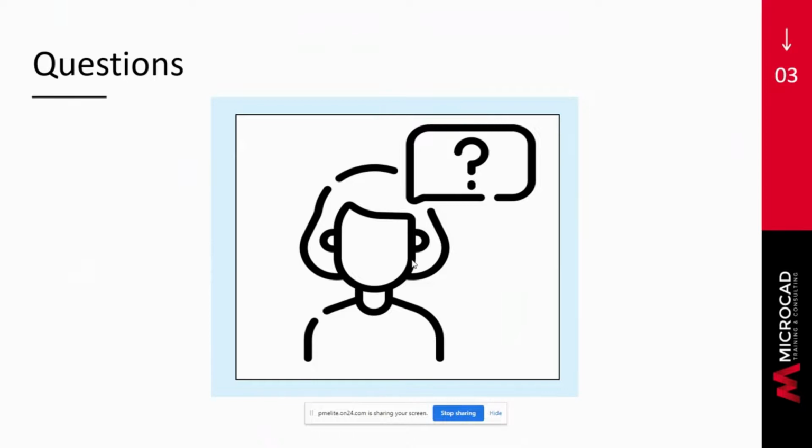Our next question is, is there a way to shift the vertical datum for profiles and corridors? Sure, I'll take that one. Yes and no. There's no specific command. I did show the datum shift for points, surfaces, and feature lines. They have built-in commands to raise and lower things vertically, but a profile object does not have a similar command.